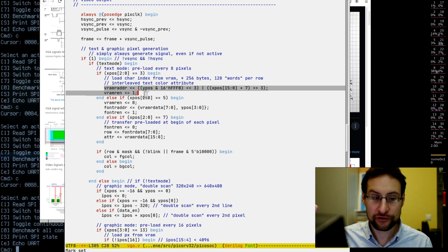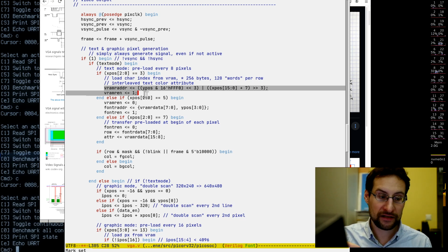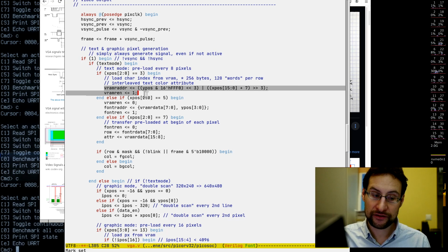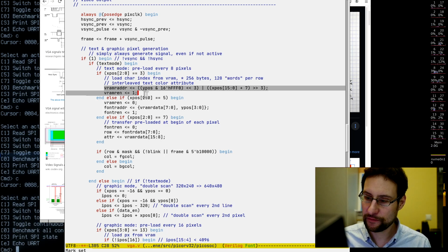I need to figure out another day if we can attribute this signal for Yosys and ICE timing to validate this. However, right now this would fail. Earlier, before my design became so complex, this signal would validate as good at 28 megahertz or even 32 or 36. But the more logic we packed in here, the more the timing dropped, obviously.